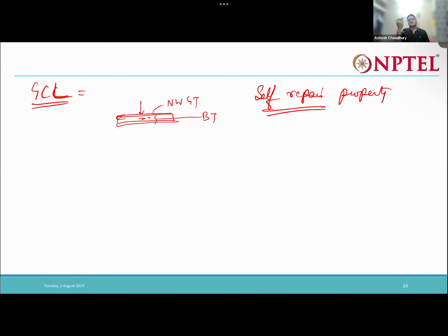All the cracks get closed, repaired, as soon as it comes in contact with water. What happens? The water gets stopped. It cannot pass through it. Right. So bentonite is a natural substance which can be used as a geosynthetic material. Okay. Next we have geocell.